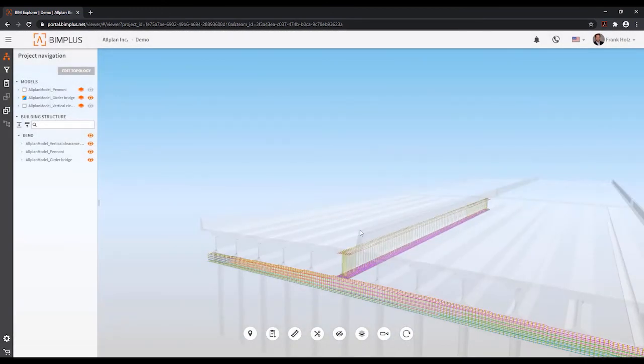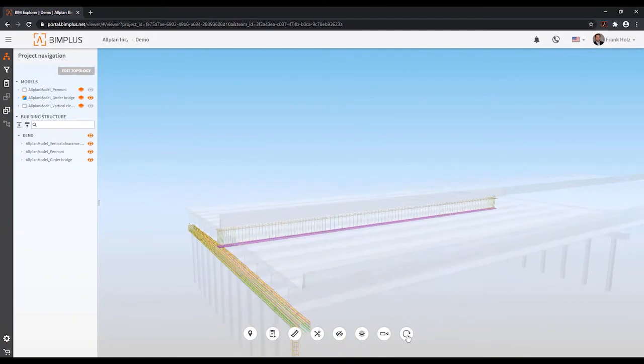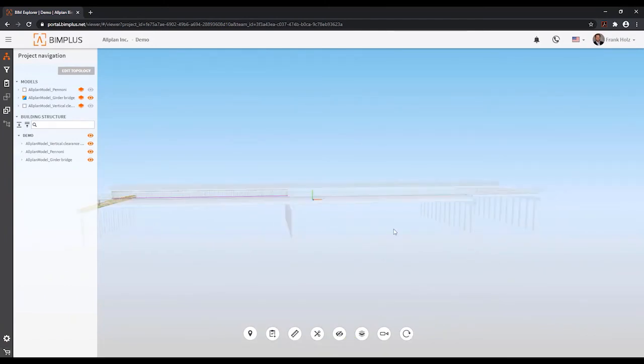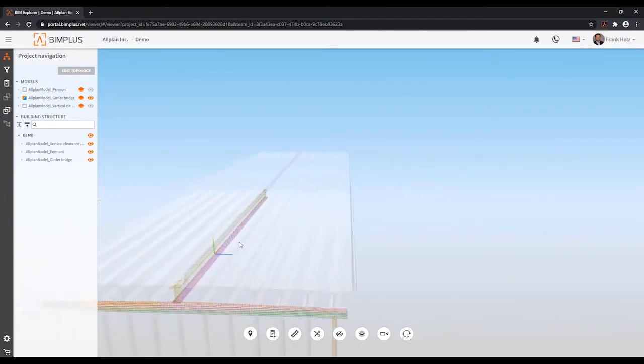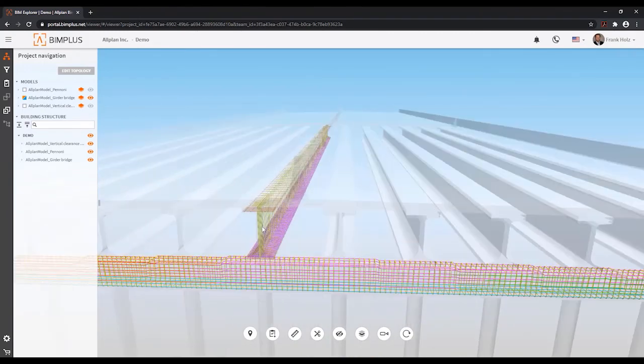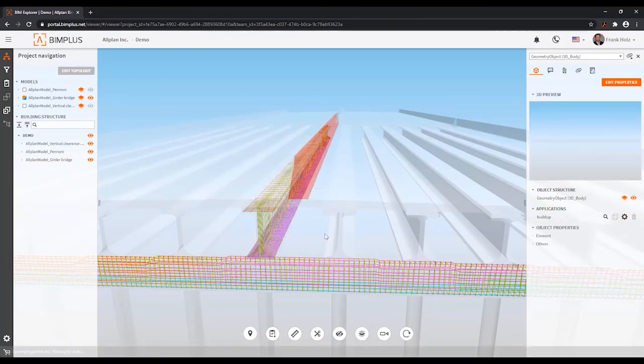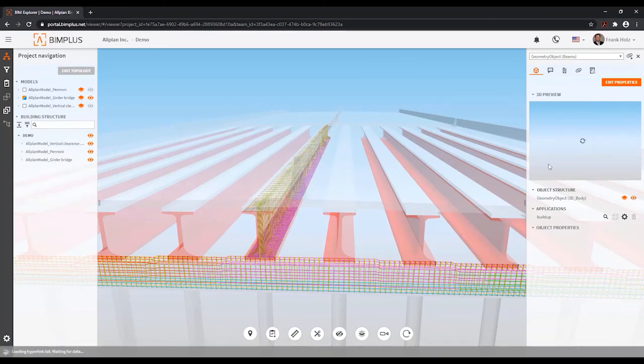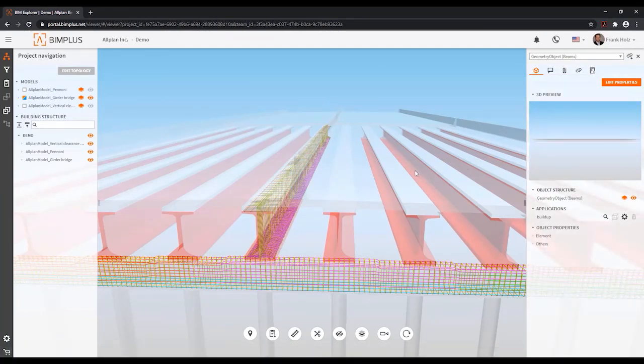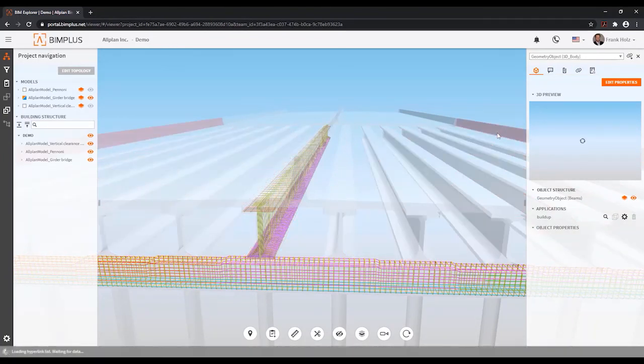This is a previous iteration of our model. And as Frank mentioned, it is a freemium product, but the base version, the free version of it is already quite capable. You're able to query individual elements, take dimensions, cut cross sections, do conflict checks. It's a very capable model review tool. It can be pressed into service by construction contractors as well, but really its intent is as a collaboration platform during the design phase.